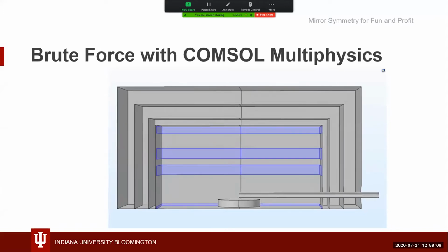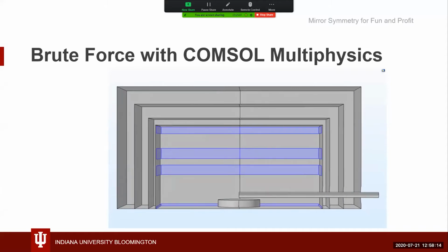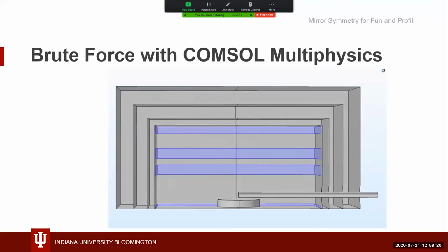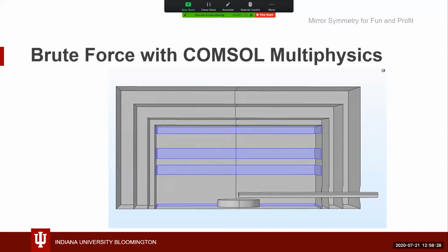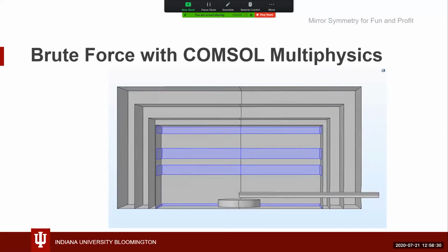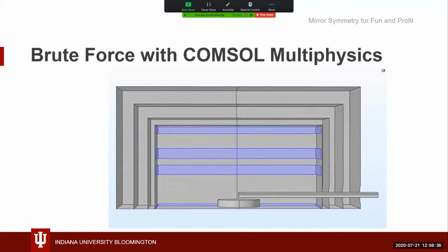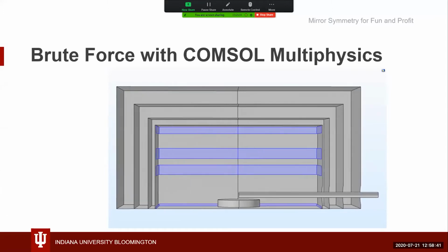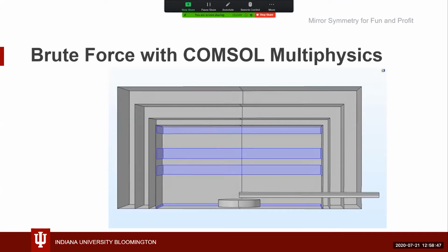So this is an animated cutaway looking at 1/4 of our magnetic shielded room and the general problem statement of what we're working with. We have multiple layers of mu metal, cubic layers of mu metal shielding material, and we want to apply current in some distribution on the inside of that innermost shielding layer in order to generate the most spatially homogeneous magnetic field in that cylindrical holding cell at the very bottom.